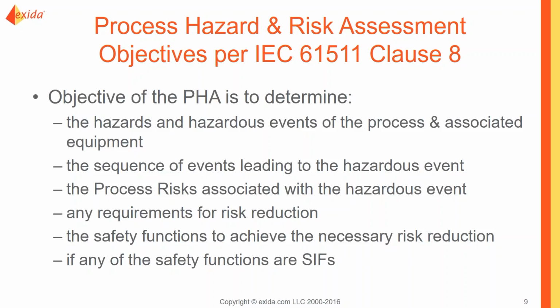And are any of these safeguards considered SIFs, so safety instrumented functions? For instance, addition of a safety relief valve may successfully reduce your risk, but it's not required a SIF and therefore not part of your safety instrumented system. This is important when you go into the design phase.